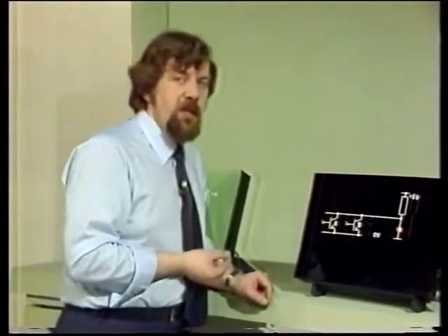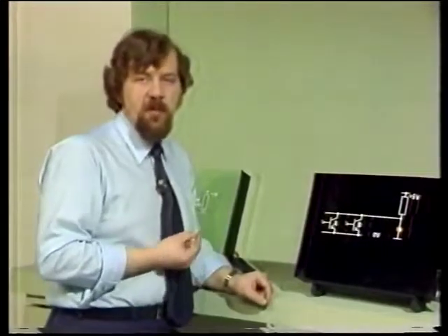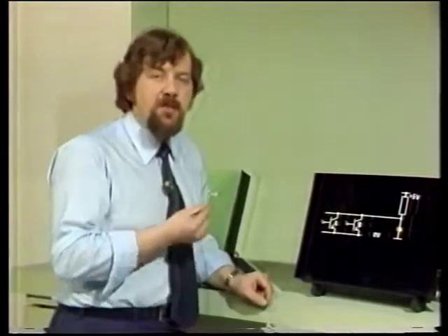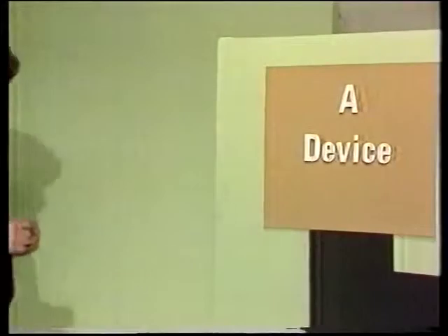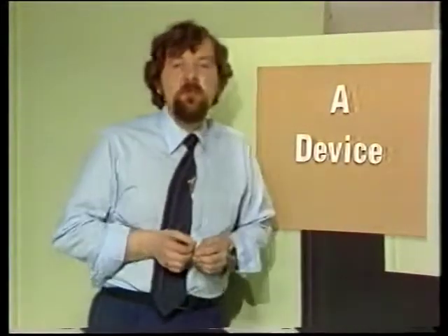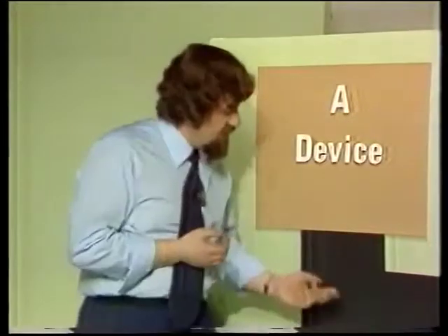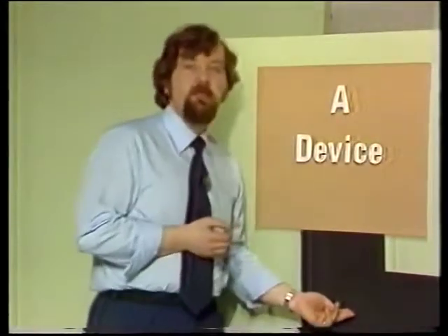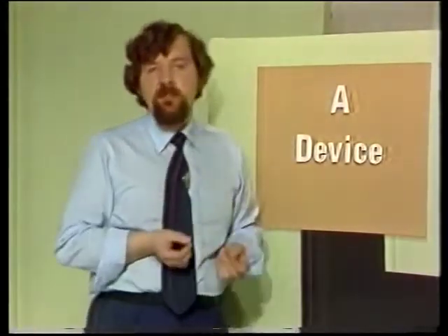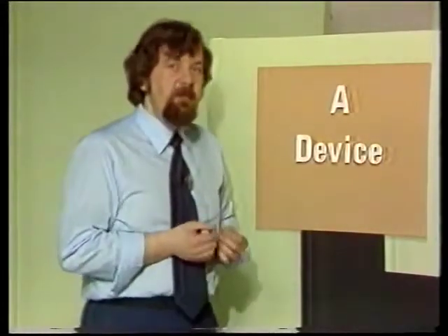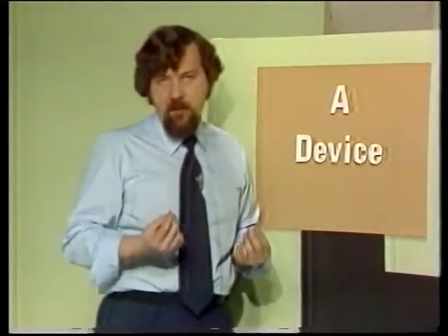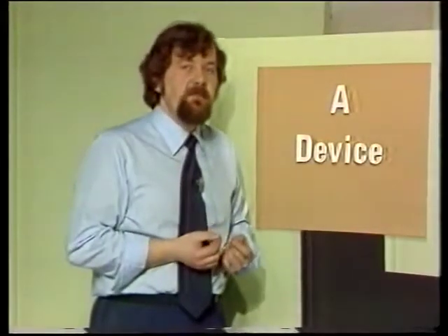Before I finish talking about outputs, there's another property of the bus structure that I must cover. So let's go back. Well, this property is called bidirectionality. It means that information can pass in either direction along the bus. This is a feature of most bus structures, and it implies that both the input and the output from a particular device share the same set of wires.